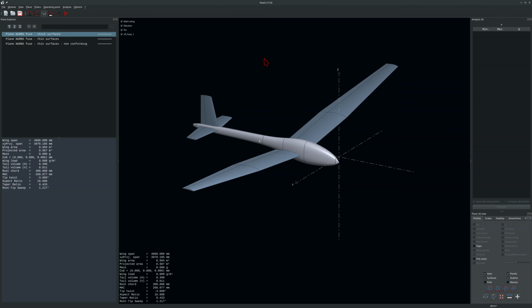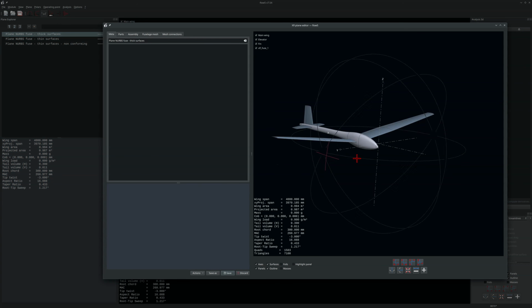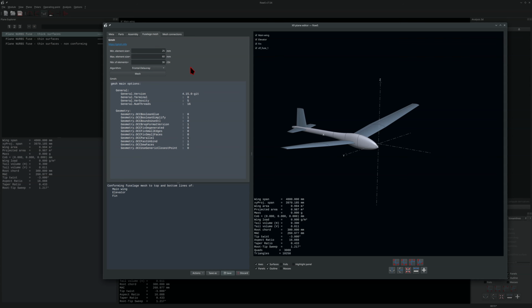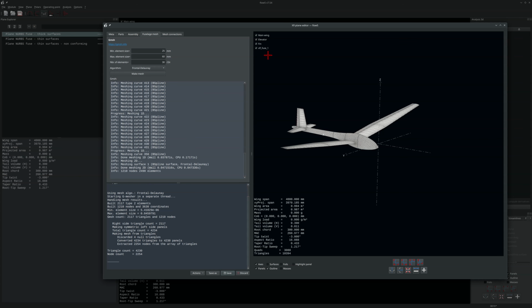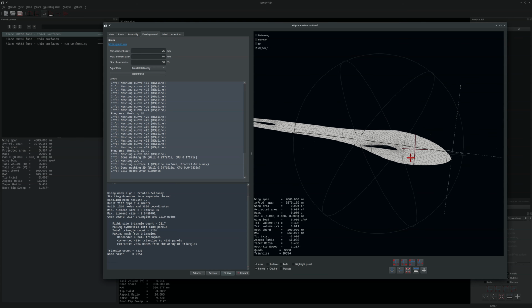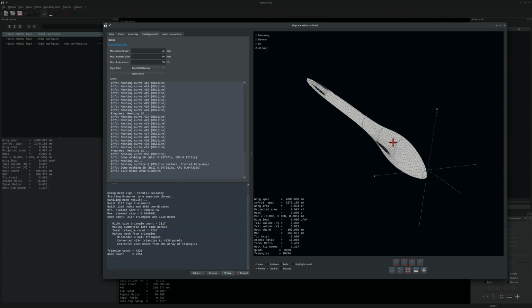Alright, let's edit it. I'll leave everything unchanged except that I will assemble it for fixed surfaces and request a mesh from Gmsh. Let's hide the surfaces in this case and request a mesh and see how it goes. I'll hide all three wings. Well, we can see that Gmsh has built for us a fuselage mesh which conforms to the wing mesh, and we can imagine that the assembly of all four meshes, the fuselage mesh and the three wing meshes, will form a closed volume for us.